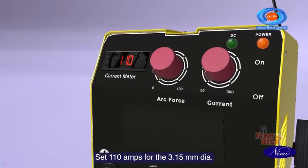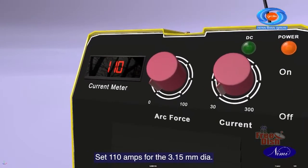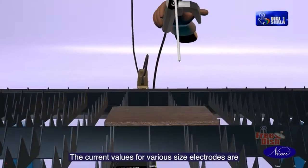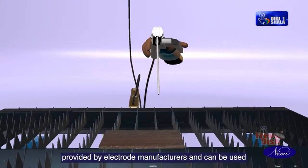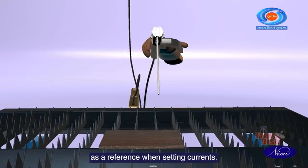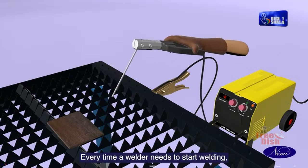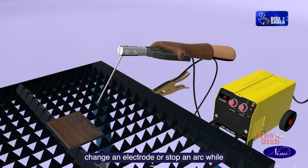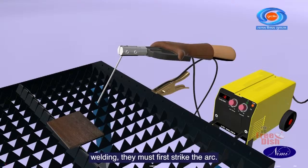Set 110 amps for the 3.15 mm dia electrode. The current values for various size electrodes are provided by electrode manufacturers and can be used as a reference when setting currents. Every time a welder needs to start welding, change an electrode or stop an arc while welding, they must first strike the arc.